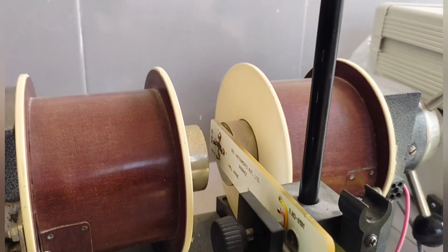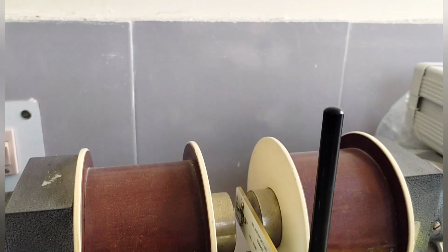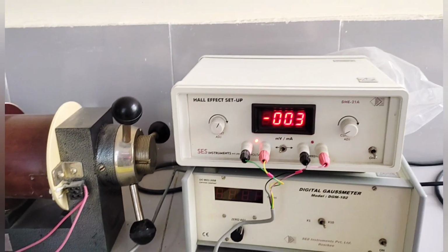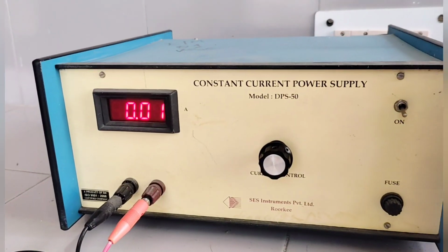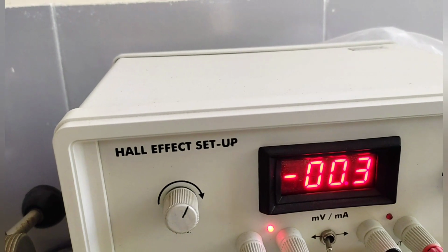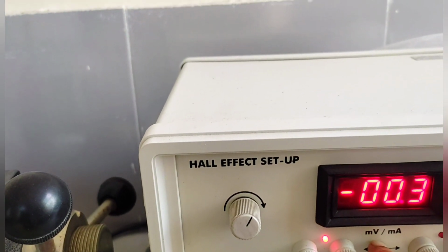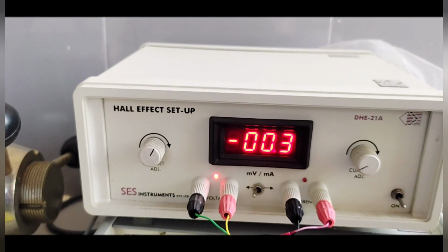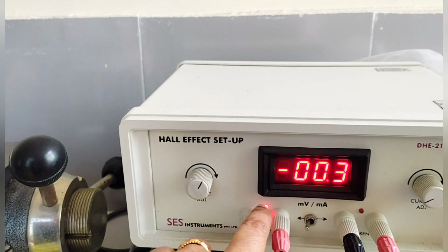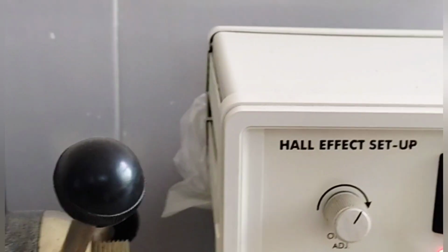We have to set the semiconductor inside the magnetic poles, and now we can see that the magnetizing current is 0 but we are getting some initial Hall voltage reading. This is the voltage reading in millivolts. This is the Hall voltage we are going to measure from here. It will be noted down as the initial Hall voltage, and it will be subtracted from every reading.